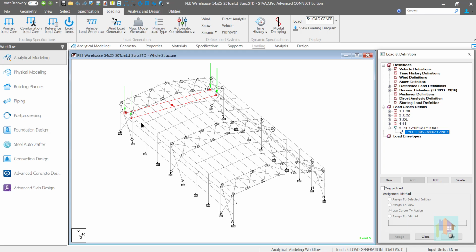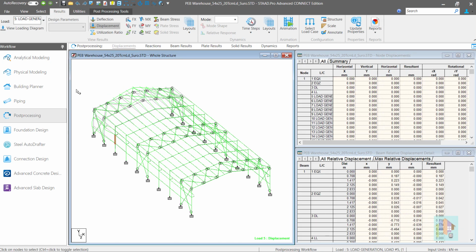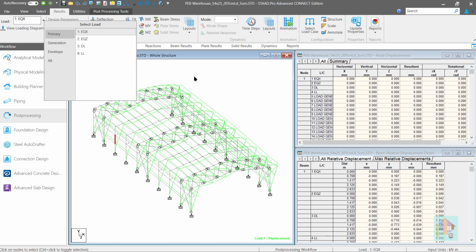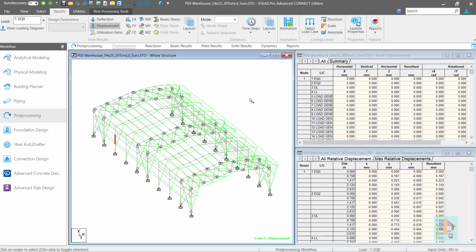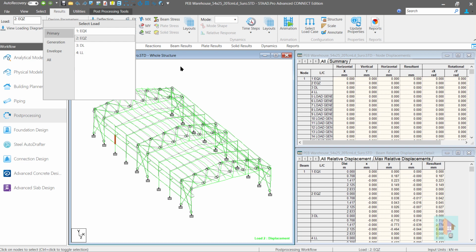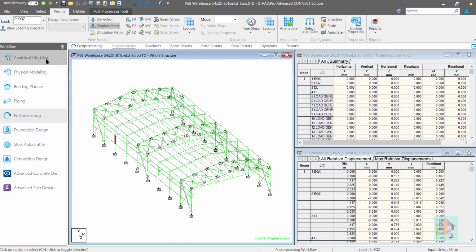Also, this gantry is not an isolated component, rather it is a part of the entire structure which supports the crane and transfers the load to the column. When the structure is subjected to an earthquake, along with all other structural components, gantry girder also moves laterally. For realistic design of all the components, including column, bracket and gantry, we need to combine this crane load with other gravity and lateral load case.